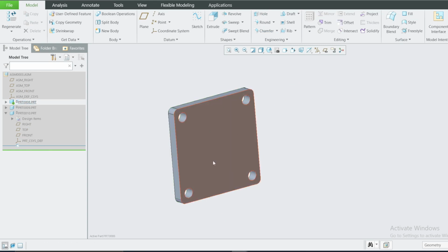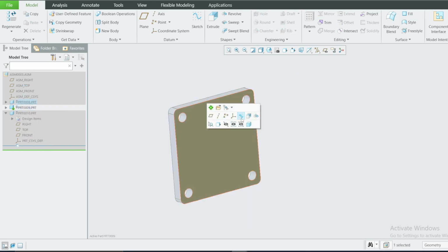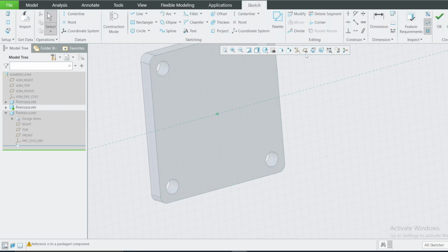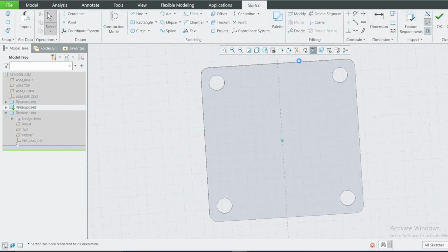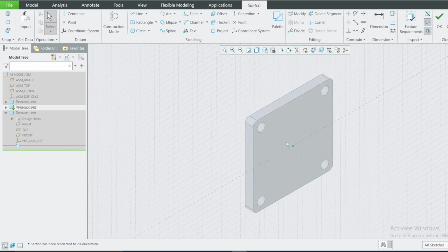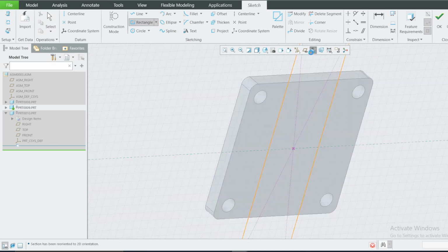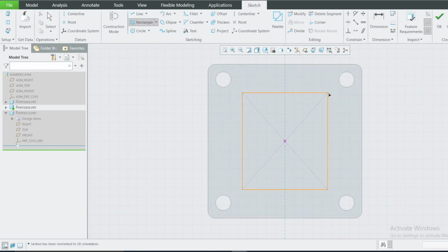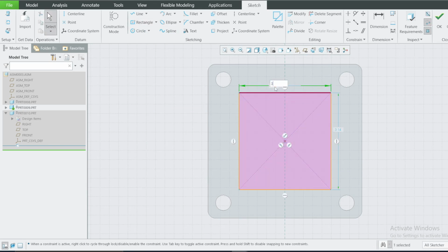Next, we need to go to the next part, activate. Next part, click here, sketch, view normal to you. Basically, Control D to go isometric. Then I need a center rectangle here, like that. Let's view normal first, like that. We need a 3-inch versus 3-inch.